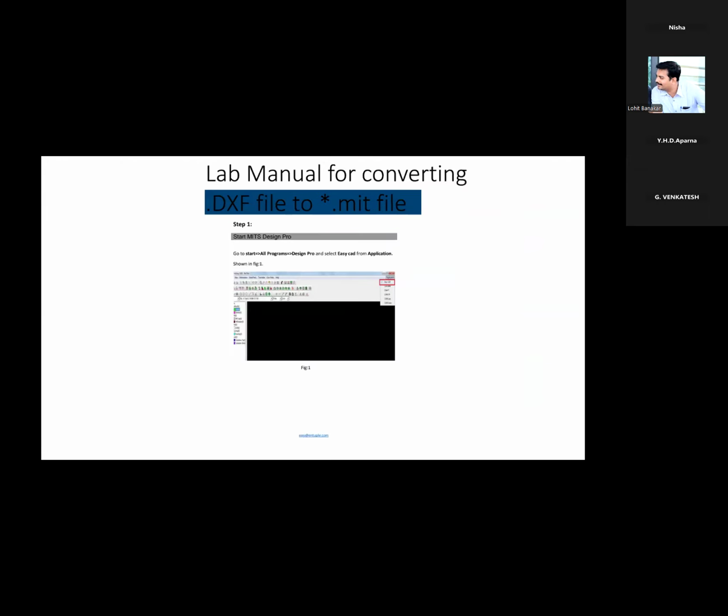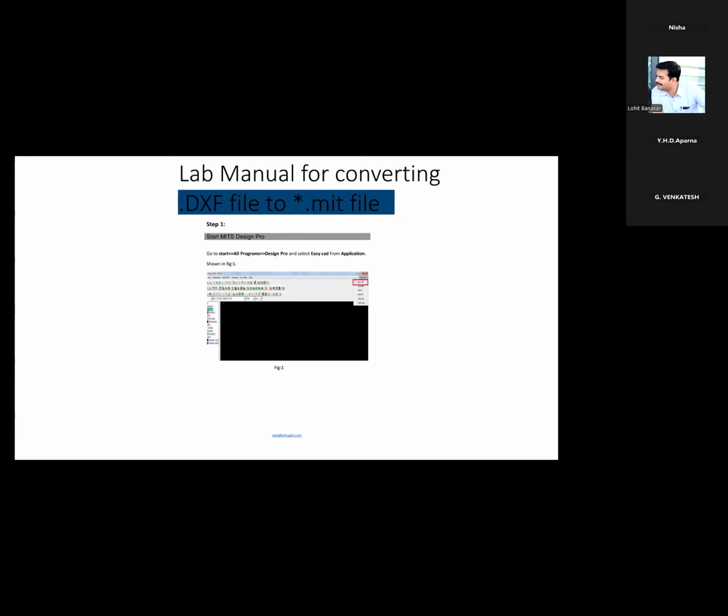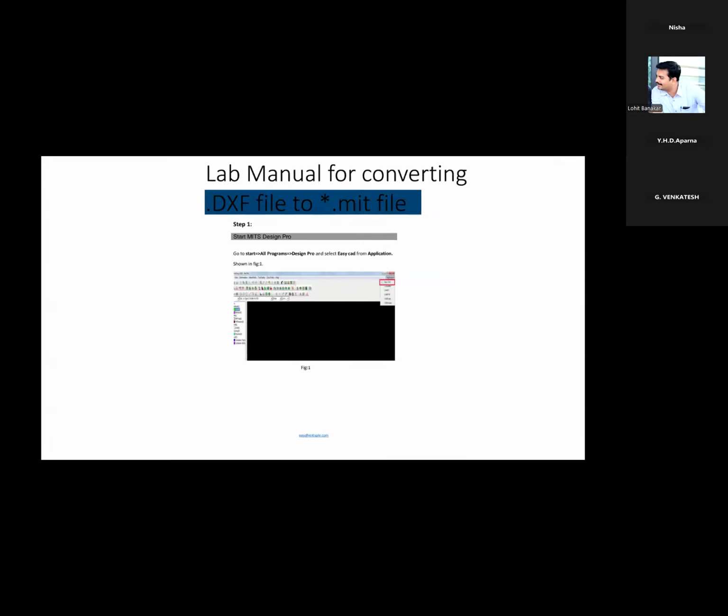And the manufacturing of antennas is available at the Vignan campus in Duvvada. So how to manufacture the antenna? Once you design an antenna in HFSS or CST, first save this file, and next the antenna should be converted. So once the design of the antenna is completed, now we have to convert it into a DXF file. Once the DXF file is converted, what is the procedure to change the DXF file to an MTS file?